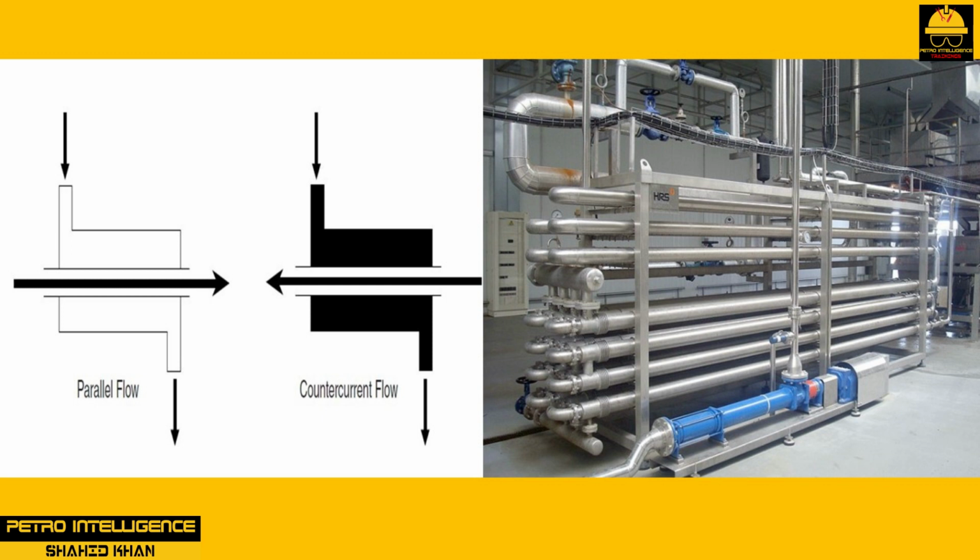Static films produced against the piping limit heat transfer by acting like insulating barriers. The liquid close to the pipe is hot, and the liquid farthest away from the pipe is cooler. Any type of turbulent effect would tend to break up the static film and transfer heat energy by swirling it around the chamber. Parallel flow is not conducive to the creation of turbulent eddies.